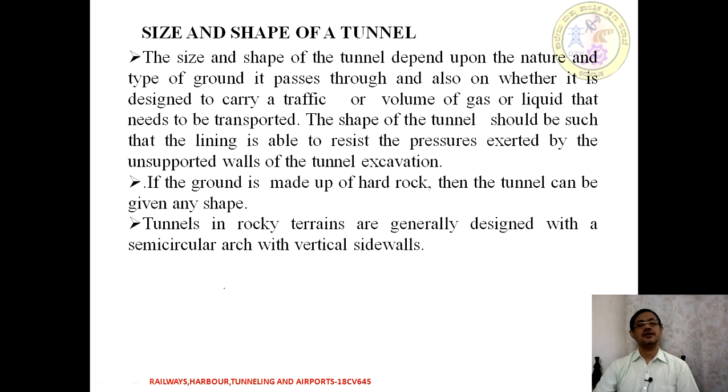Tunnels in rocky terrain are generally designed with a semicircular arch with vertical side walls. As we know, the arch resists more thrust coming over the structure. That is why we use semicircular arches in rocky terrain.